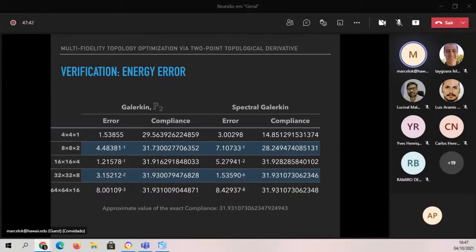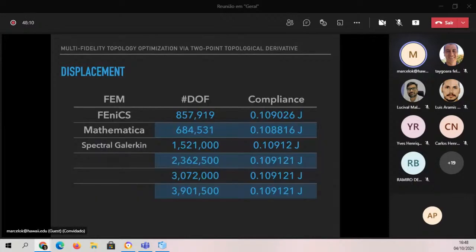In general you have an infinite number of tail numbers there. But you see that I have all numbers already correct for the compliance at 64, 64, 16, whereas the usual Galerkin method using a Lagrange P2 finite element still only has up to the third decimal place correct. And I need 6 decimal places to do the validation. And so that's why I developed this spectral Galerkin.